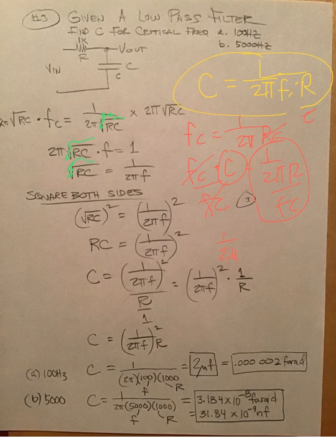1 over 2 pi R divided by F sub C over 1 needs to be converted to a multiply by flipping this. I think I left the R out. What did I do here? The R, 2 pi R. I left the R out. So once you do this multiply, you end up with the formula that I suggested you would get up here, and that's what you plug your numbers in.